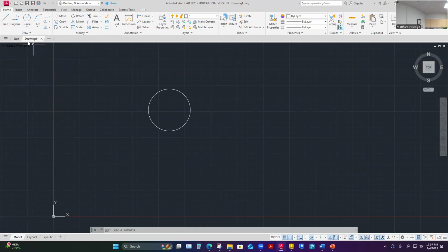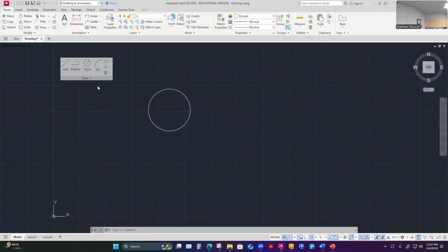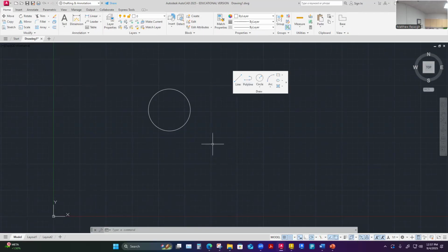What it's showing you is that I can actually have control over this to move it, not only slide it around where it lies here on the ribbon menu, but I can pull this thing and place it into my drawing area. It did pull the whole panel down, right? So now I have it right here. This can be strategic. I can dock this in other areas.